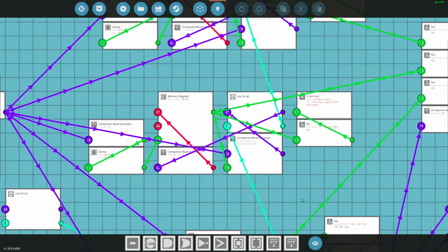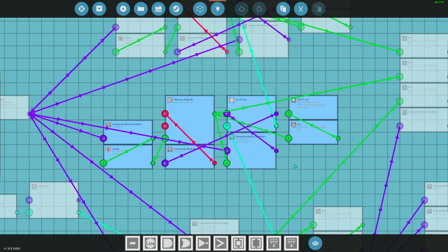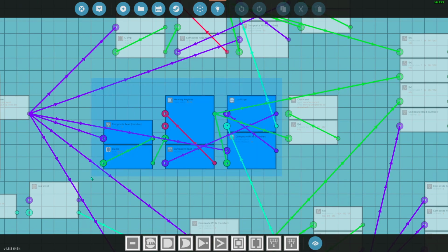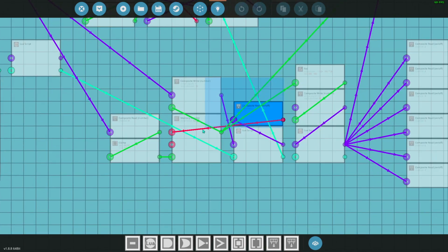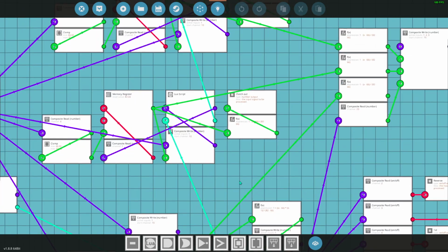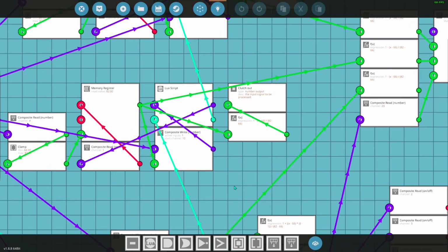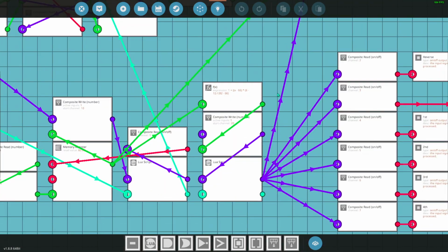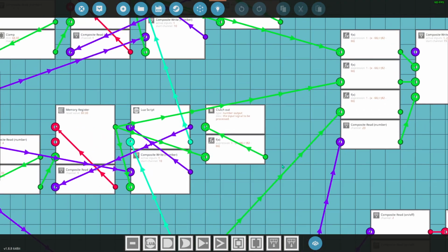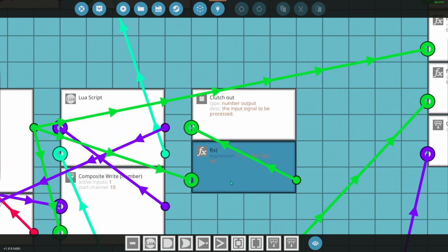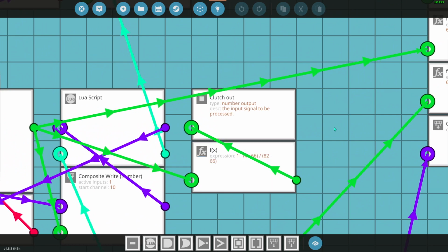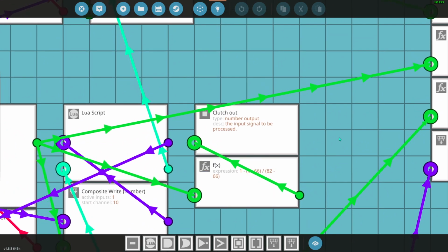So this is the exact same previous to the function as this, except instead of controlling the gear slider, it is controlling the clutch slider. Instead of outputting between 1 and 6, it is outputting between 0 and 1, and that is directly outputting to the clutch between 0% and 100% clutch pressure.